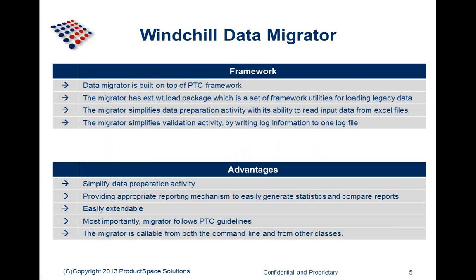So going to the next slide. Technically challenging steps in a data migration are the data extraction, transformation, and load. In order to simplify this area, we have developed a Windchill data migrator. The data migrator application is built on top of a PTC framework. It comes with a WT load package, which is a set of framework utilities for loading legacy data.